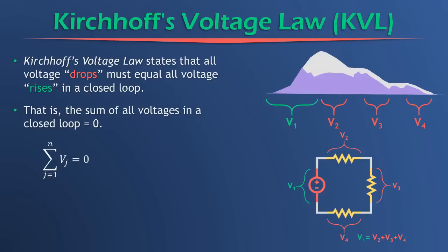And now before we wrote out an equation for each node and its associated currents, that was in KCL, but now we're dealing with KVL, and so we're going to write out an equation for each loop and all the voltages associated with that loop. So we write that out in the form V1 plus V2 plus V3 and on up to Vn, and set that equal to 0, and that's how we write an equation for a loop, and that is a KVL equation.